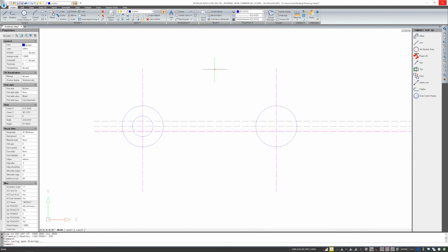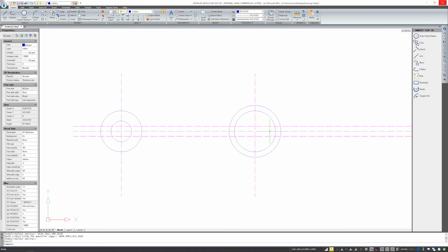But I can also use the offset option for that, which I have already shown here on the line and the rectangle. I choose only the distance, say 26 units, confirm, and show which way. So this offset can be applied both to a straight element and to circular arcs, to all elements that are in the program. When you edit an element, copy, offset, rotate, they always take over the properties of the element from which you are copying. I'm talking about properties like line thickness and belonging to layers.